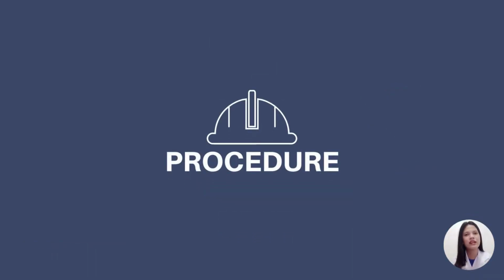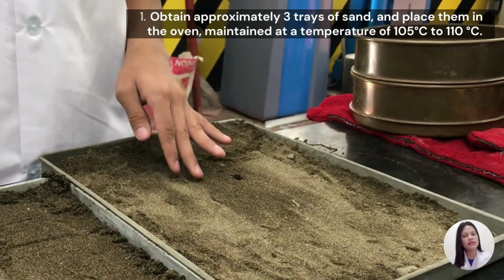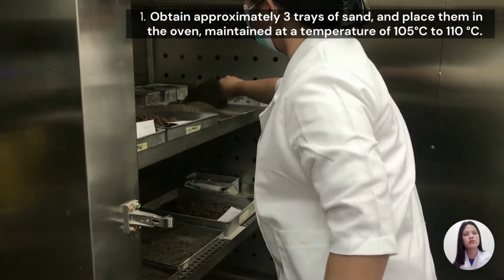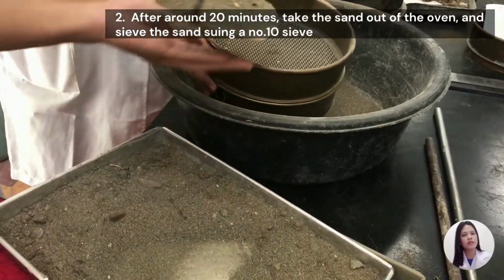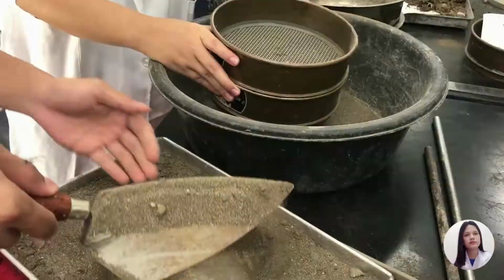In this section, I'll go over the steps we took to conduct the experiment on the field density test by sand cone replacement method. First is to obtain approximately 3 trays of sand and place them in the oven maintained at a temperature of 105 degrees Celsius to 110 degrees Celsius. After around 20 minutes, take the sand out of the oven and sieve it using a number 10 sieve.